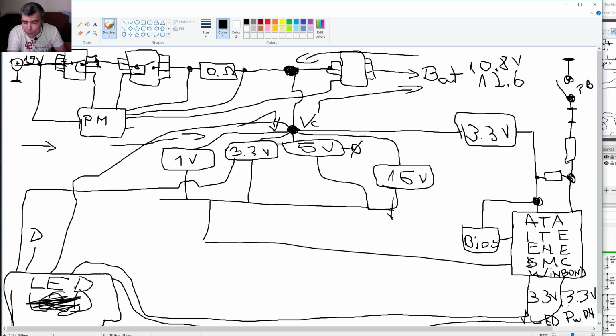Yeah. But one is power on, one is powering up the screen, one is the dimming. You know, the screen is made less bright or brighter. Yeah. So on one pin you have 3.3. If on the other pin you have 0, you have no light. If you have 1 volt, 2 volts, yeah, you have low light. So that's very important, on these two pins there have to be signals. Yeah. But this is a LED screen, yeah. So we are not speaking about the big inverter from LCDs. But even on that one, it's the same thing.